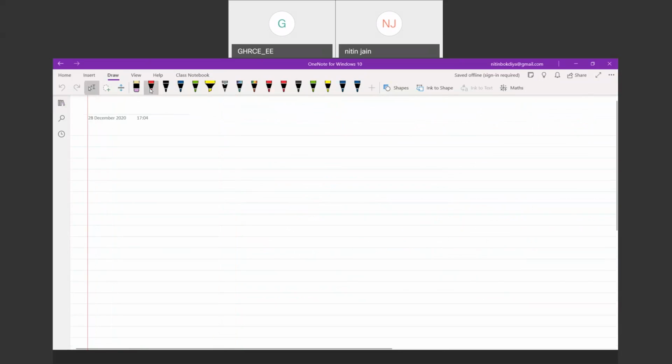One is at the output, and the second one is at the input. The output point is known as the sampling network, where you sample the signal for feedback. And the point where you mix it with the input is known as mixing.